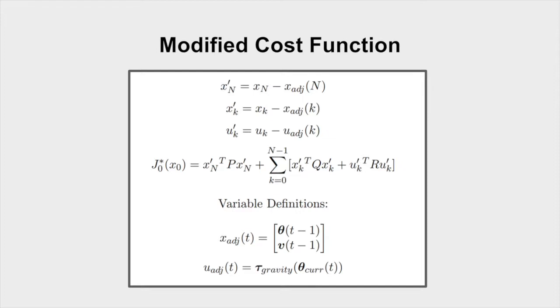Previously, weighting the torques in the cost function would cause the robot to droop along the trajectory because it would be reluctant to provide any energy to counteract gravity. After this change, however, we were able to weight the torques more reasonably and attempt to penalize jerky movements without letting the arm droop.